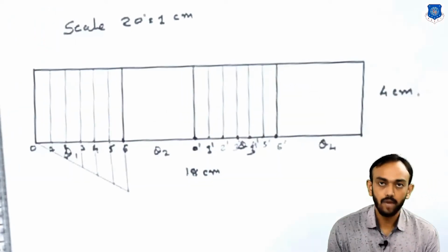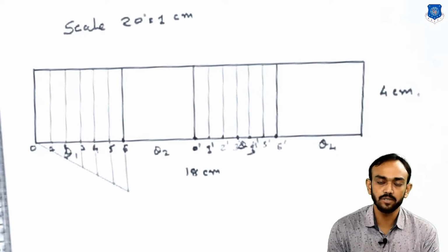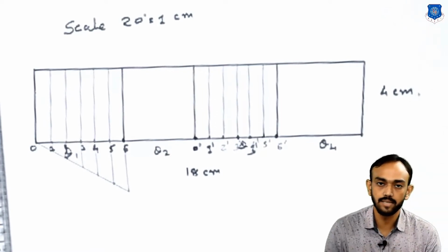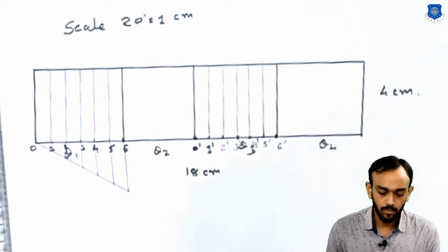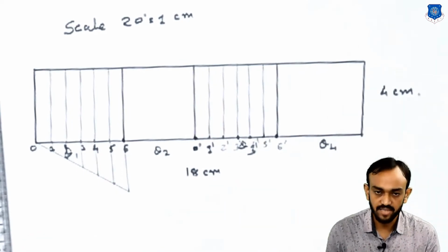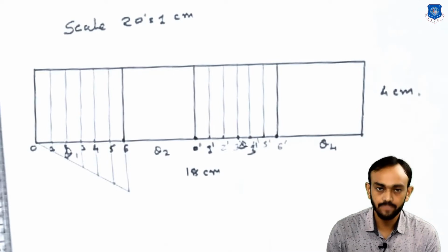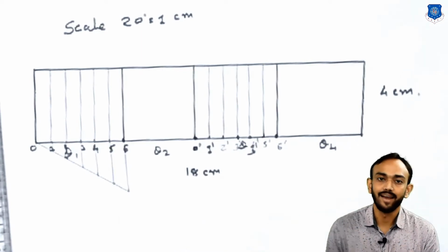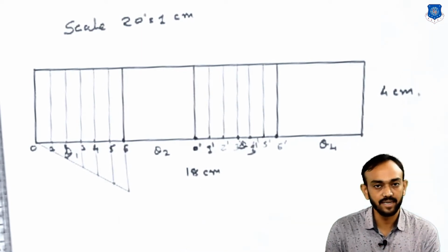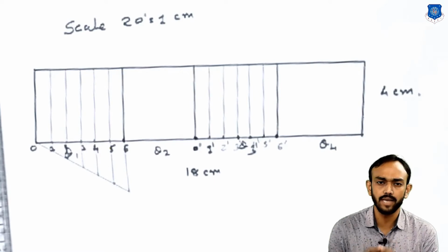Okay, now up to this point your procedure will be the same in all the examples of cam profiles. Whatever example you are solving, up to this point make the 18 centimeter by lift rectangle, divide the rise, means the whole 18 centimeter, into theta 1, 2, 3, 4, then rise and return, 6 partitions of rise and return. Up to this point all the examples will be the same.